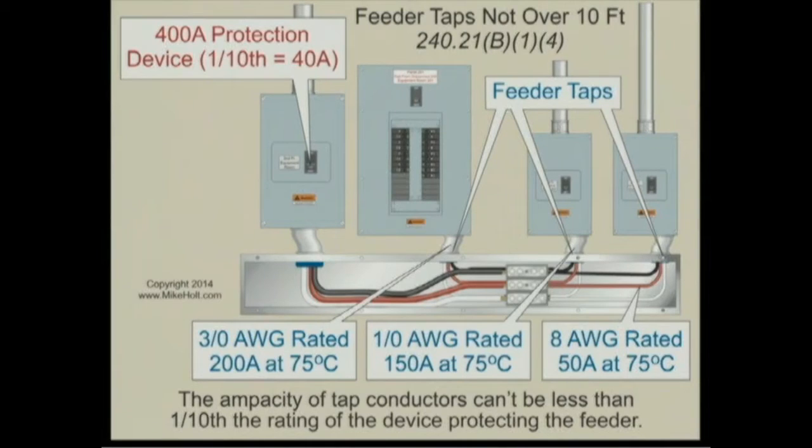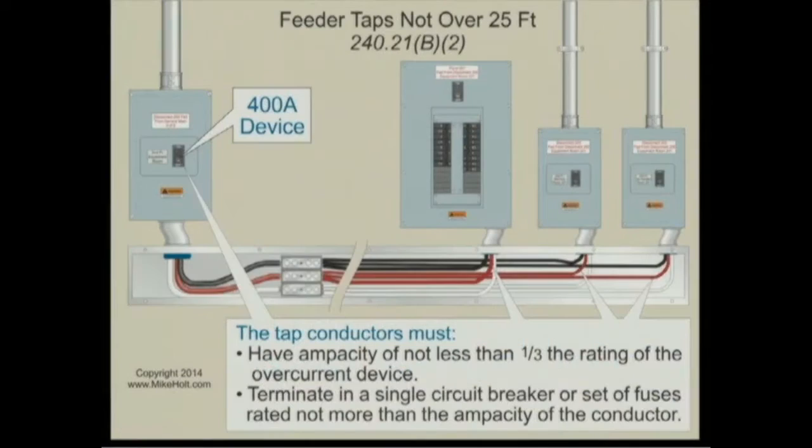If this was a 50 amp breaker, well, it all depends. We'd have to double check that example, that the text says we're using equipment that's rated for 75 degrees C. Then I can size the wire to 75 degrees C. We just have to double check all those rules.